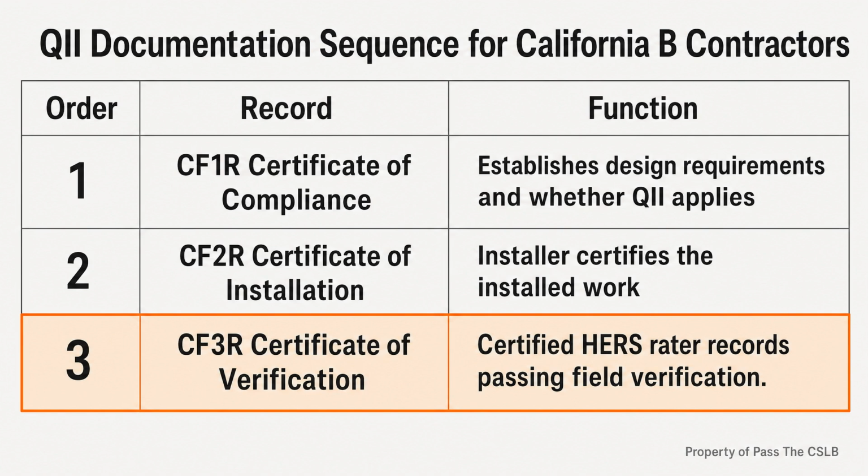A wall can contain the specified insulation and still miss the quality standard because the batt has gaps, has been crushed, or has no continuous air boundary around it. I treat required verification as a before cover hold point. That phrase is worth remembering. Before the board goes up, the contractor needs to know what must remain visible, who must verify it, and which record closes the verification step.